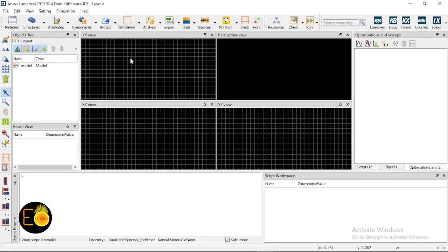This simulation is basically the domain within which your calculation should be confined, because this medium is infinitely extended, so only that particular domain you have to consider. Mesh is basically the additional grid lines that I mentioned. There are default mesh lines, or default grid lines, available within this region.